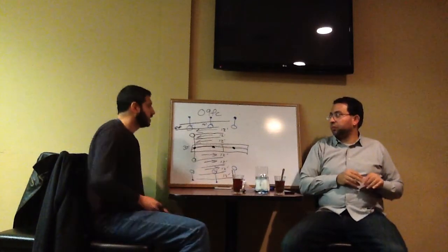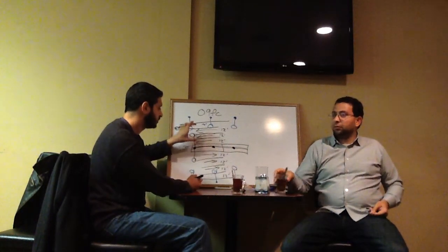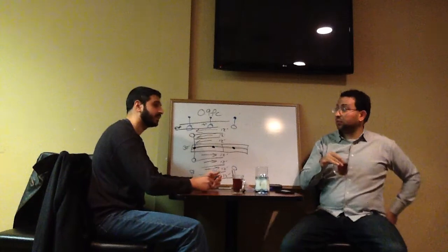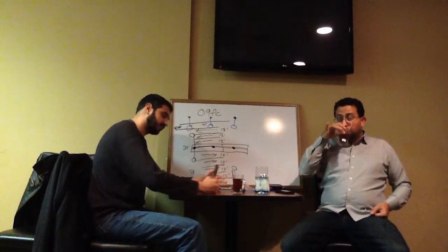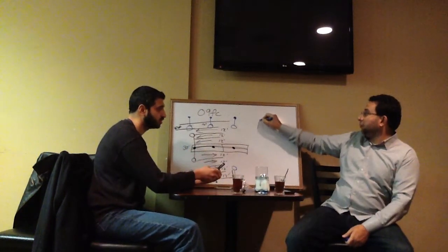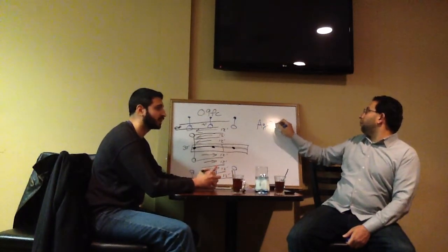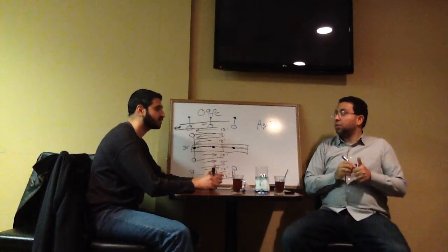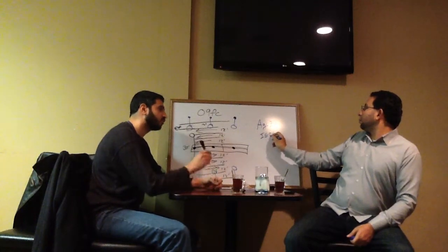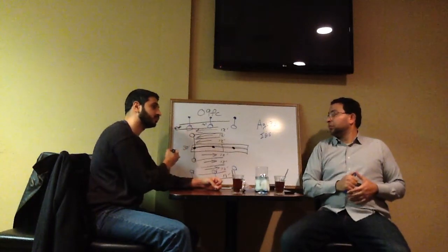Okay. So, as a designer, what you want to do first, once you figure out your roadway size, is go into the AGI program. I would pick a generic fixture, like the standard fixture that I always use, since I've done so many projects. But if you have a specific fixture, you can pick that. You need to load what's called an IES file into the program. Without that, you can't really do much. An IES file is kind of like an instruction sheet for the program, based on the specific light and model that you pick for your design.